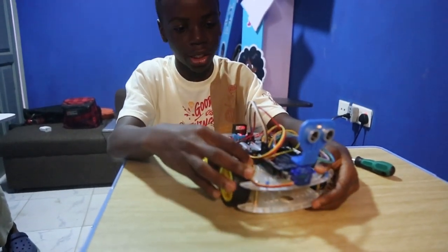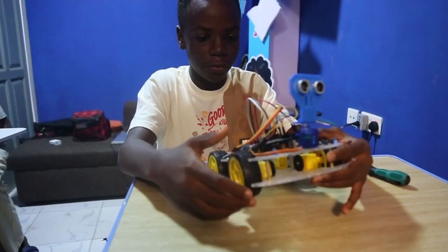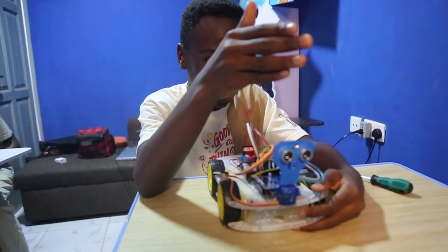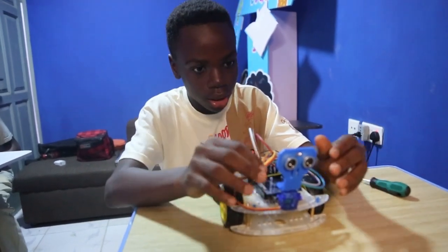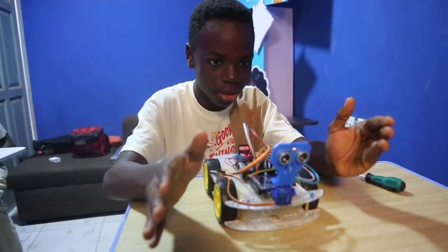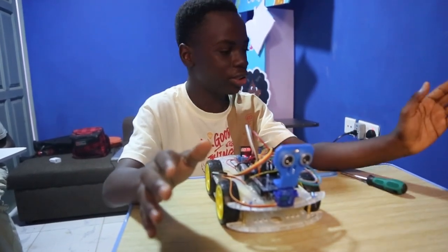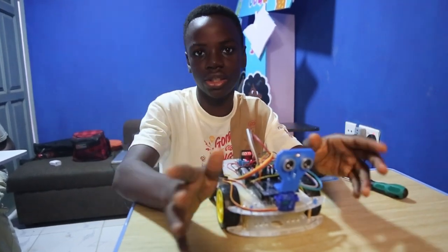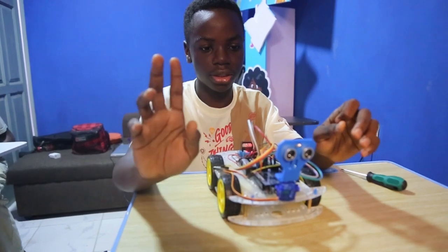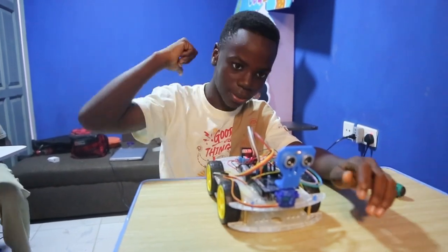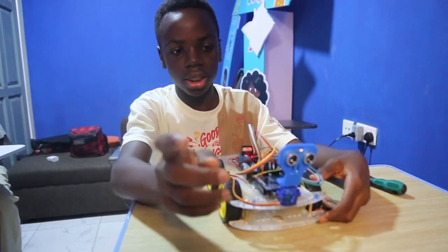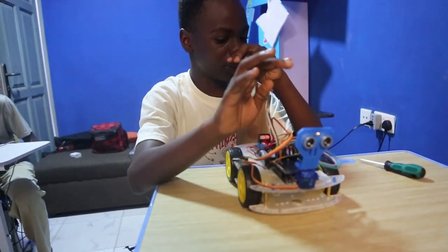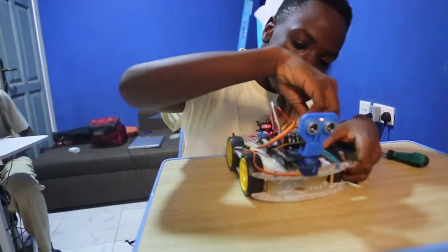This is what happens when it starts working. The motors start moving forward constantly, and the sensor looks for anything in front of it. If it sees something, the motors stop. Then it will look left and right. If there's a way to the left, it will turn left and go there. If it is to the right, it will turn right and go there. If not, it will turn around and come back. It turns because of the servo motor.